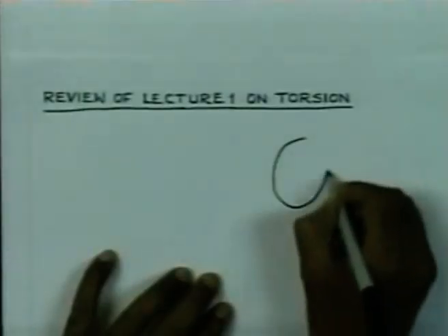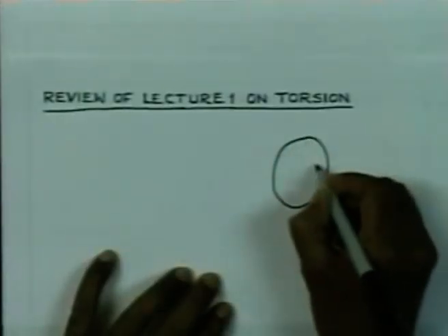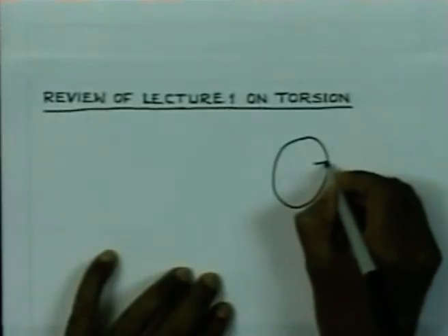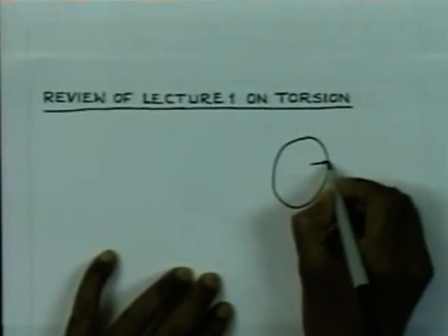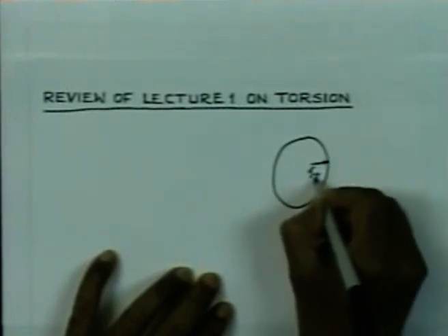and we have noted that the section is subjected to shear stresses, which have a typical feature: shear stress cannot be acting normal to the boundary. If you have a section like this, what we have found is that at a point on the boundary, the stress which is normal to the boundary acts in the radial direction.